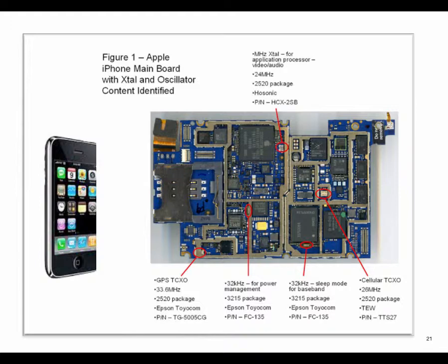You can see how modularly designed this thing is, right? Everything on the board is a separate function, and to keep designs reusable, each one of them has its own local clock to work with. It also lets them meet specifications. If you look at specifications for a network protocol, it will come with very tight timing requirements, how much jitter is allowable, and you have to meet those. So by the time you are done with all of these things, you do end up with a pretty crazy set of timing requirements.